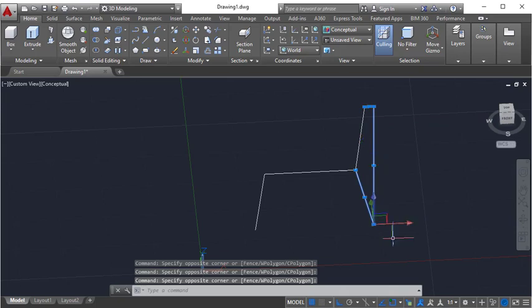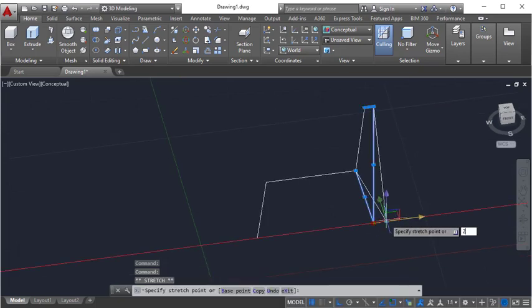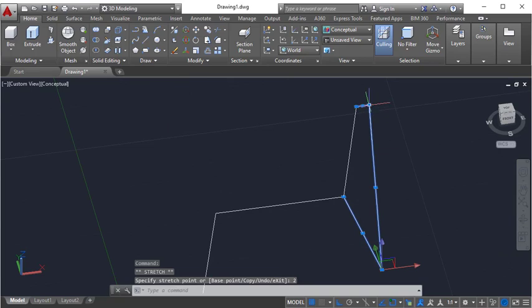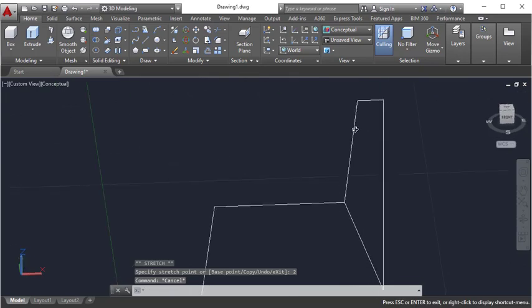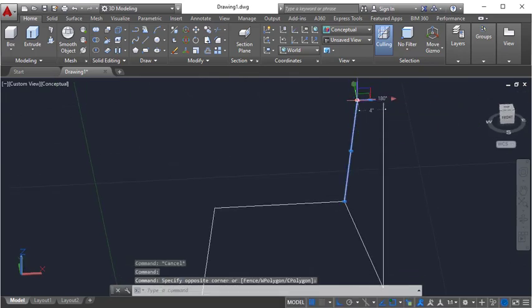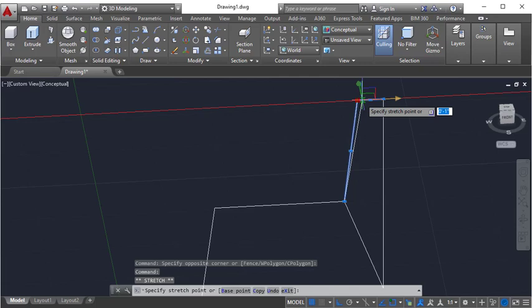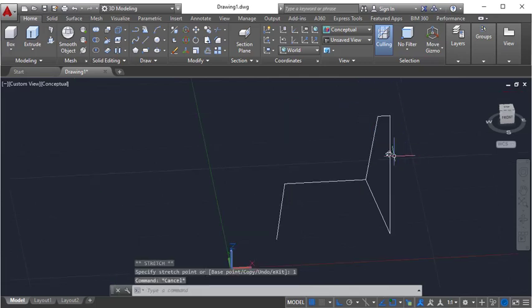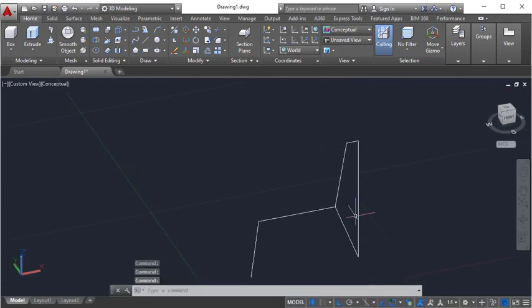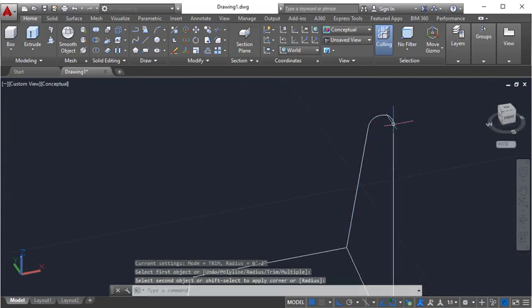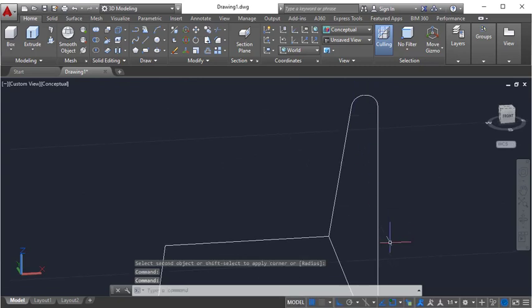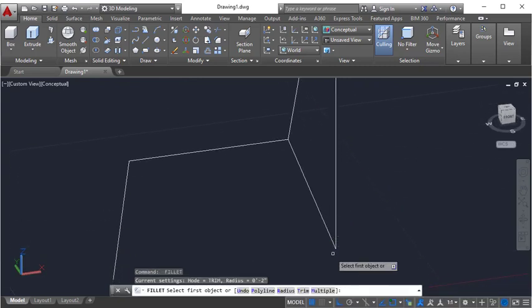First of all, snap the gizmo here, and I will move 2 more inches, and the same with this one, 2 inches, so it will increase to 4. A little bit, 1 inch, 1.5 will work here. So F enter, radius 1.5 inch, first line, second line, space, first line, second line, space. Space is the command for repeating the operation, and again space,